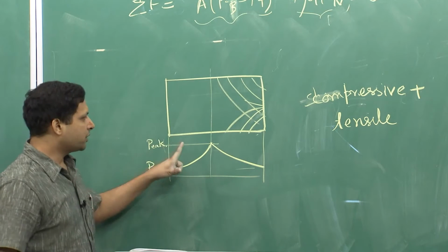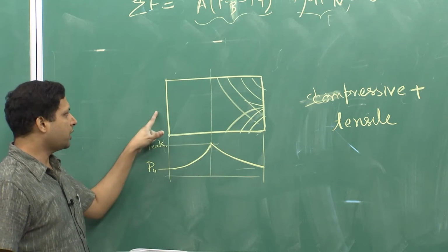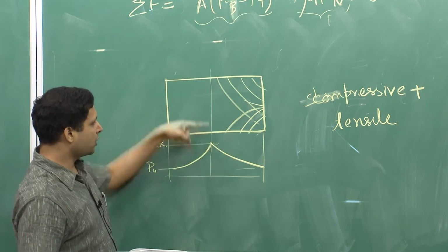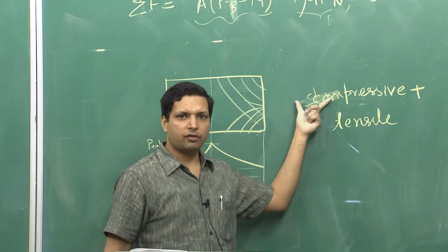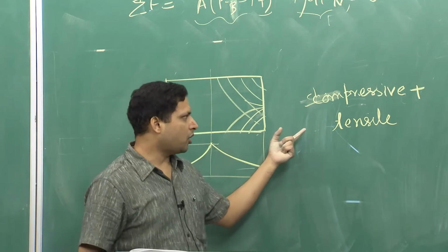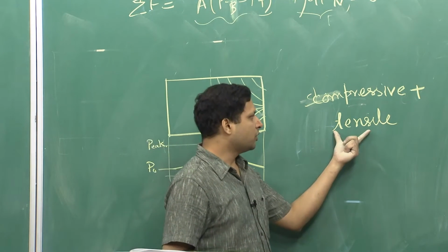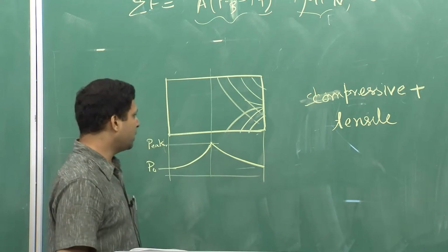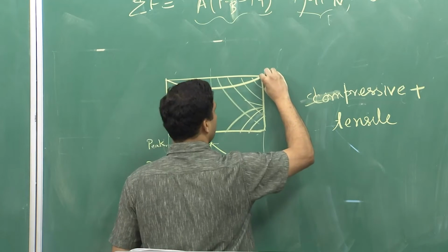these two facts: the fact that there is a pressure variation because of friction along the edges and because there is friction along the surface, there is another pressure distribution, and the fact that after you have compressed and you remove the piston, the material or the component tries to relax, and hence there is some amount of tensile forces. So, the two things add together and lead to a shearing phenomena.